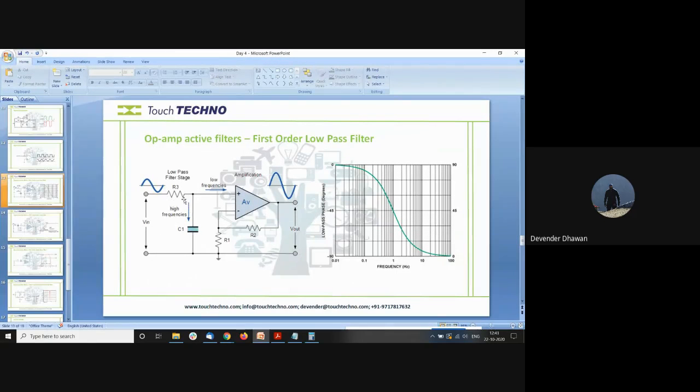This is the circuit that we need to make the RC. Now this RC will basically be doing the low pass thing, because the capacitor attracts higher frequencies. It will ground all those higher frequencies and pass our low frequencies to the op amp, which can then be amplified if we put in some amplification resistance, which you can see here. So let us quickly make this.